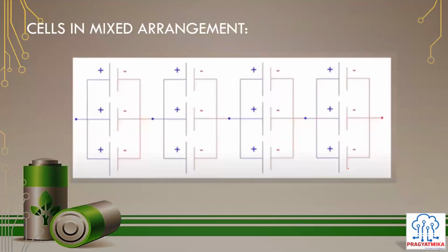But once you are going into battery pack design, it is not only the series connection or only the parallel connection that you will be doing. In the case of prismatic cells nowadays, it is possible that you will be doing only series connections. For example, you are making a 2-wheeler or 3-wheeler battery pack using a prismatic cell of 90 Ah capacity. You have to do only series connections, and you will have the required battery pack in your hand. But if you are using cylindrical cells for the battery pack, cylindrical cells have limited capacity like 3 Ah, 4 Ah, 6 Ah. The voltage will be in the range of 3.7, or 3.2 for LFP. So you will have to do a mixed arrangement of series and parallel.